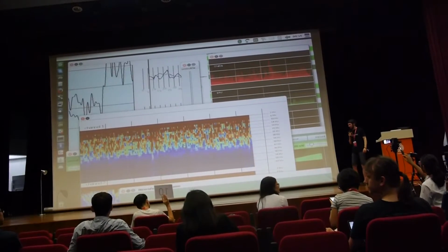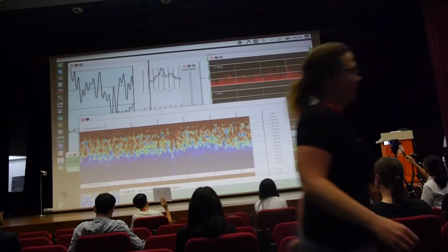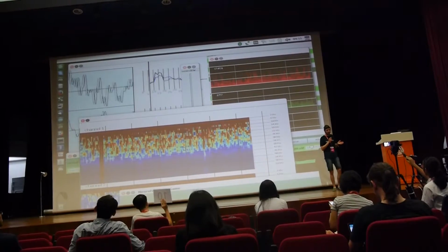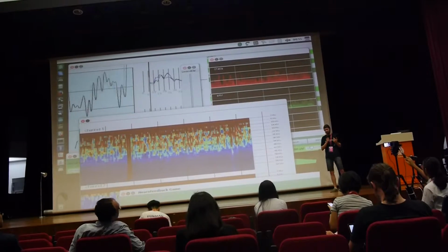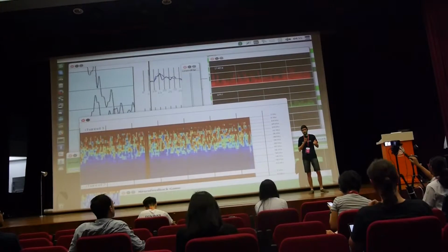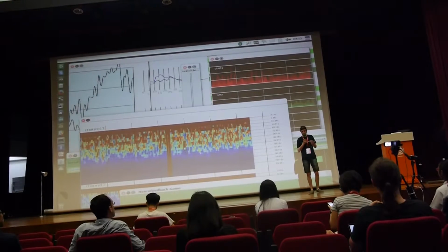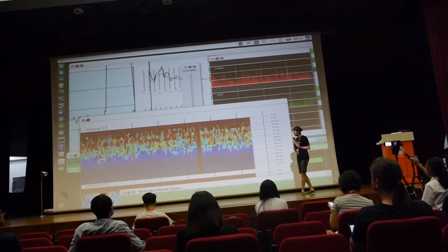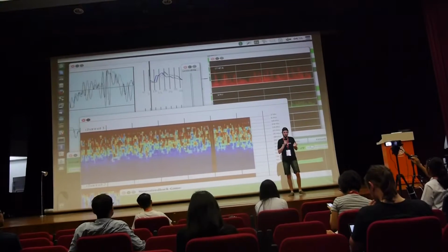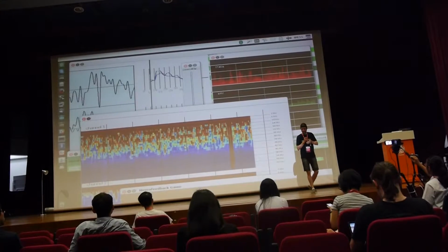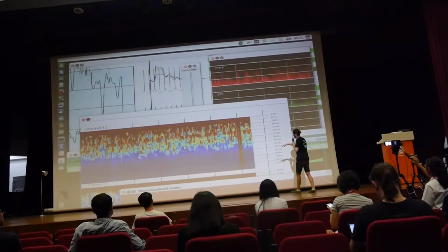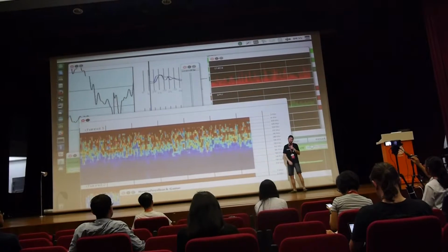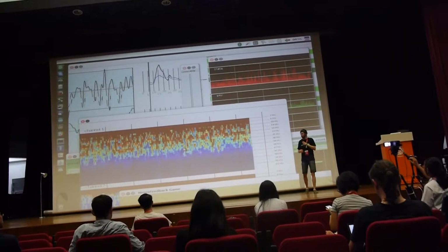Okay. So what's important is to have a range, let's say, starting at 0.1 hertz and then going all the way up to 40 hertz, 50 hertz or something like that. The most common activity you have is between roughly 0.something and 40, and that's why we also made a bandpass filter here. You can see right now the filter mode is on, and so it goes roughly only to 40 hertz. This is really where we want to look in particular.